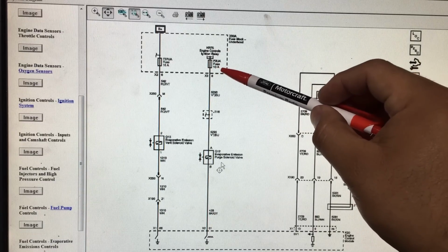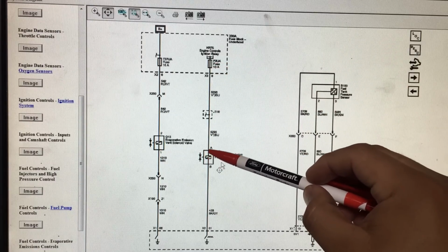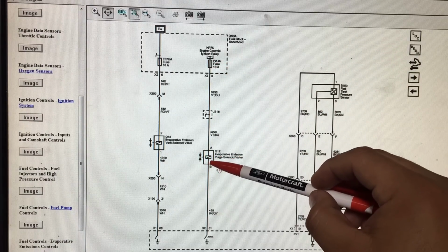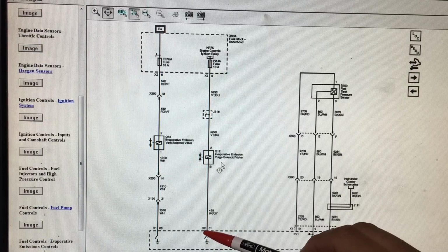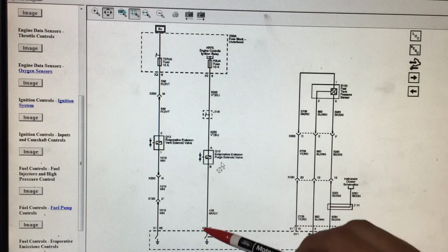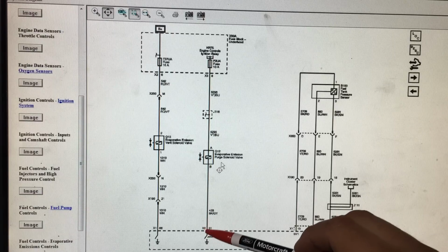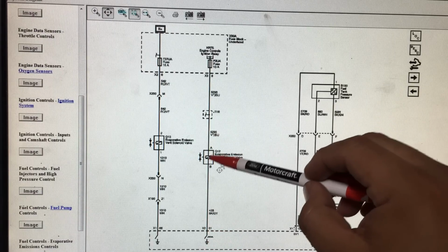This has power on as long as the ignition is on. Power should be going through the circuit, going through the coil winding of the solenoid, and reaching the engine computer at this pin. Now, we could say the engine computer has an internal voltmeter, and it's always looking for that power because it wants to know that that power is there and ready for when the computer wants to ground the circuit and energize this coil.